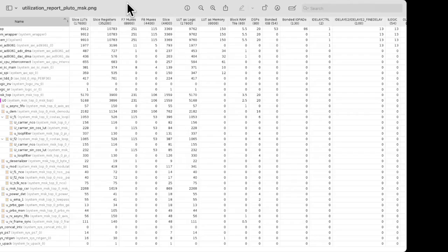There was a question. We did not get that to happen right off the bat, and we were a little bit worried about that. Also, our FIFOs are very large, so that we can clearly see them in simulation and in hardware testing. We're going to optimize those to say, when you're going over the air in any particular situation, you only need this much for the FIFOs. That will give us back at least some of the BRAM to use on other things.